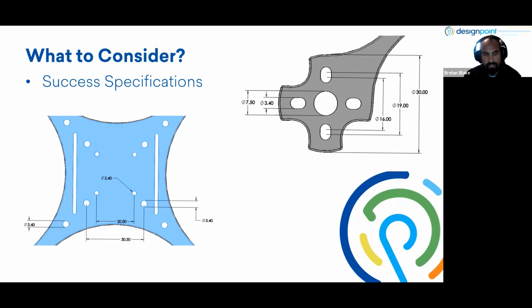Some of the things that we had to look at were the tolerances for the holes. We use all 3mm hardware the whole way around for the quadcopter. So we wanted to make sure that we had a little bit of tolerance there, so we could actually slide our bolts through the holes without having to do any post-processing or Dremeling out of those holes. In the center of our frame, in the lower left-hand corner, we have a 4-bolt pattern for electronics, as I was saying before. So we can incorporate smaller mini electronics as well as full size electronics. This gives the versatility to use whatever kind of electrical components that we purchased.